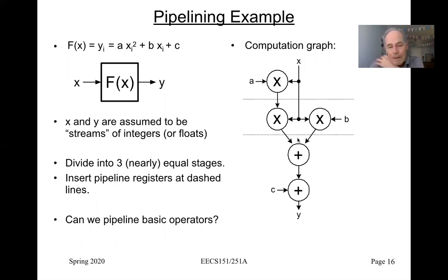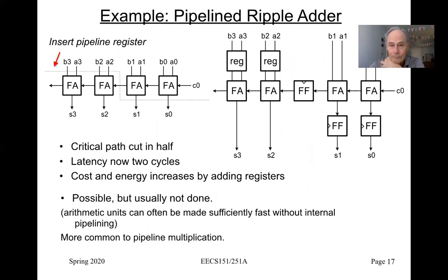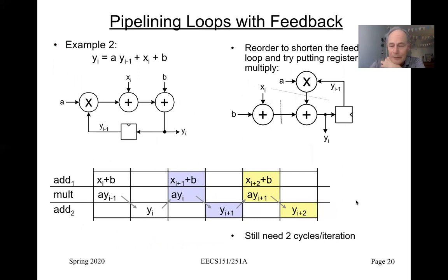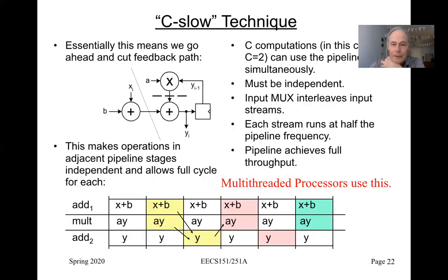Now there's some limit to how much performance improvement you can get from pipelining, for the reasons that I mentioned earlier. But when you can use it, it's a very good technique to use. So typically we do that first. When you think about finding ways to optimize for performance in hardware design, pipelining is the first thing that we apply because it comes at relatively low cost.